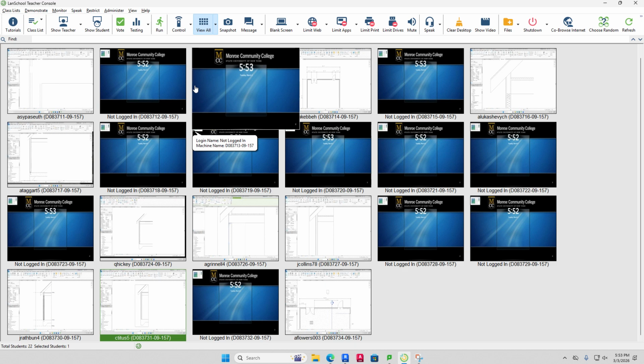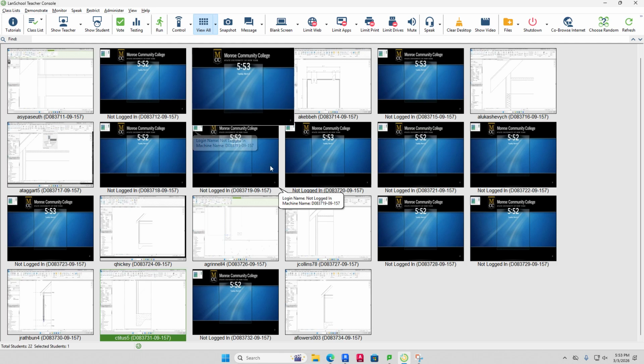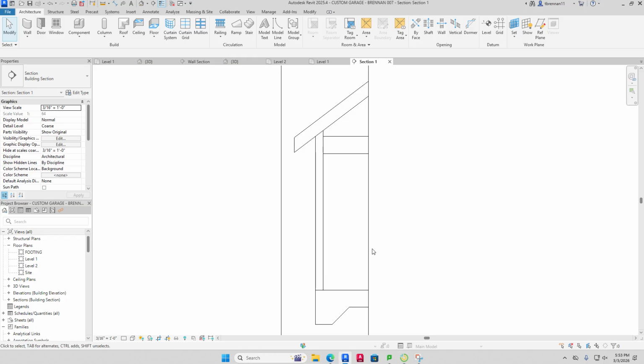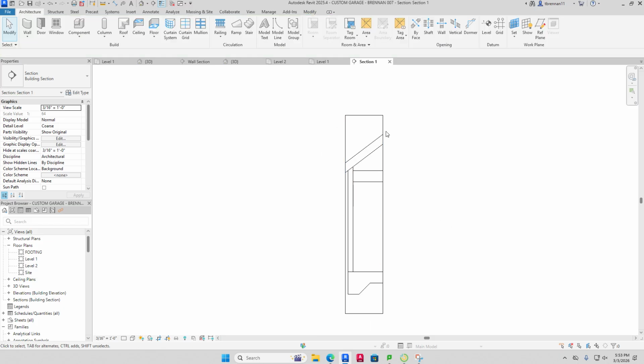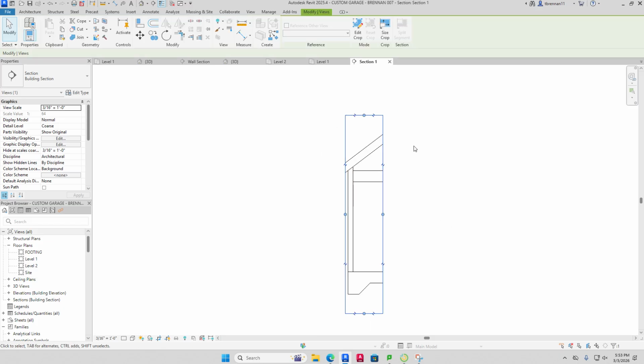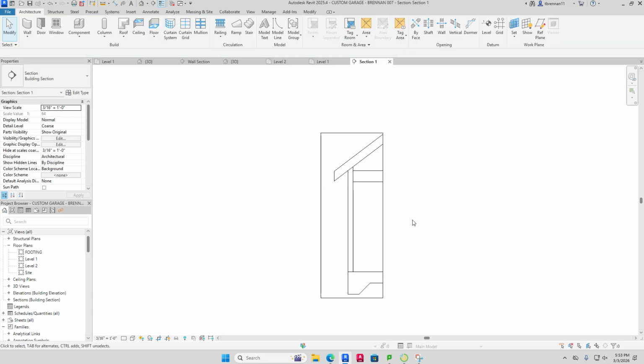Okay. All right, and we can refine this. Part of what we're learning right now is the visualization or views in Revit. You can go ahead and you can fix these and you can change it. Like, if you get into the view and it looks like, let's say it looks like this, it's kind of clipping some off. That's where if you just click on this frame right here, this is a viewport, you can actually take it and just widen it, and you can adjust it like I'm doing right now. So that is what you want to do, just like that.